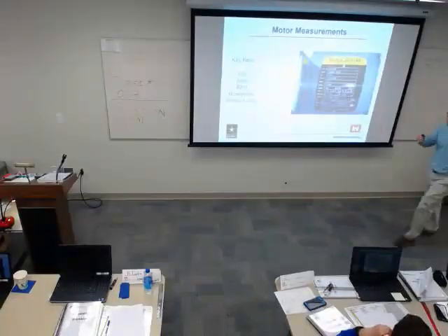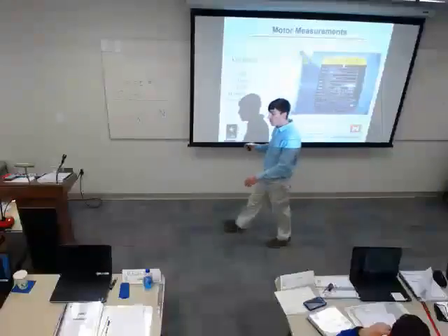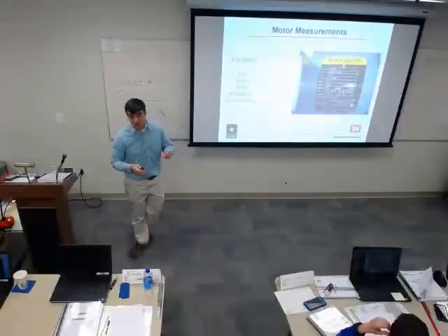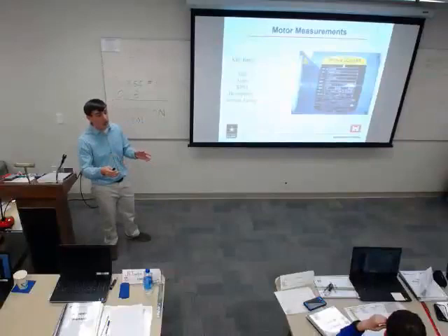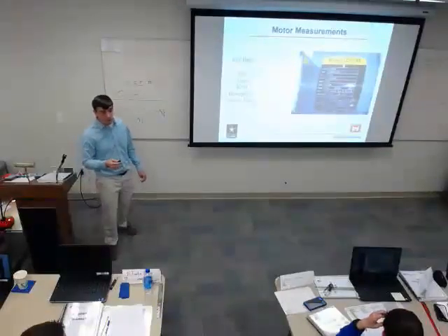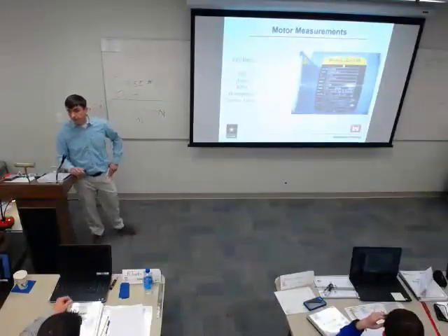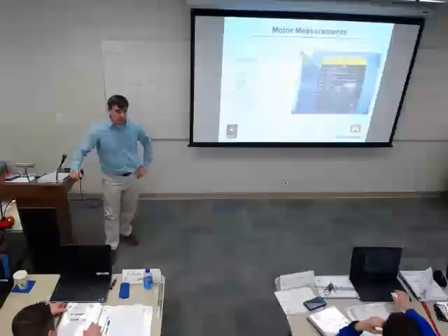And probably talking about an electrical distribution system problem, it might be a motor problem if you had a substantial difference between current or voltage on each leg. Yeah, and NEC is actually where they address how serious the difference is.